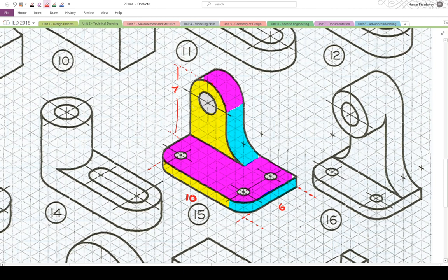You could extrude out a shape that goes up like this, but what I think I'm going to do is make a really big block on the back side, and then I'm going to take that really big block and cut it out. So I can just make an L shape like this. It's going to go all the way, oops, I went too far.